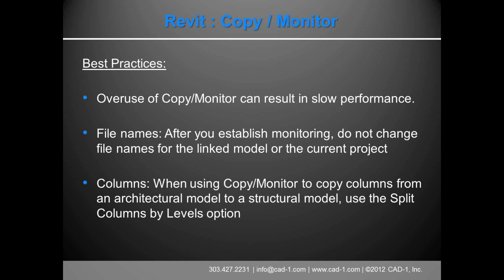Something to be aware of around file names. After you establish monitoring, it's best not to change the file names for the linked model or for your current projects. Also, if you're doing some columns between architecture and structural, if you do grids, it's best to not associate the grids with the scope box until after you've copied the grids into your host model. If you're going between architectural and structural, you can use a copy monitor tool to copy a floor from an architectural model into your structural model.